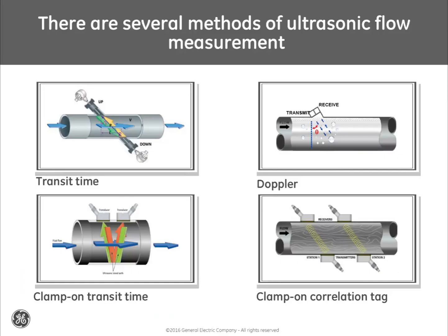Doppler was the original method for measuring flow with an ultrasonic flow meter and is typically only used in applications with very high amounts of solids or gases in a liquid medium. With a Doppler or Doppler shift meter, an ultrasonic signal is sent from a transducer and the signal bounces off a sonically reflective material such as a bubble. Assuming that the material is traveling at the same speed as the fluid, the returning frequency will be different based on the velocity of the sonic reflected material.